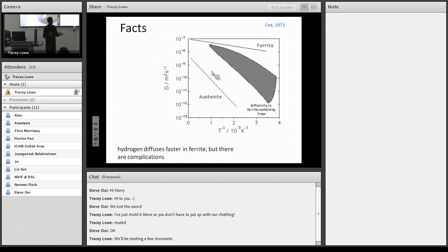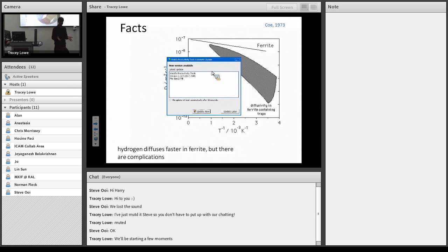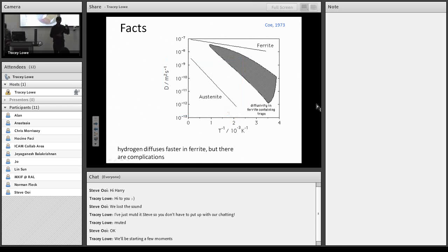So you might ask yourself the question, how can we hold hydrogen in a steel cylinder which is ferritic? I mean, you do it, right? Any ideas? How can you hold hydrogen in a steel cylinder? The diffusivity of hydrogen in ferrite is huge. Well, this is atomic hydrogen. Molecular hydrogen hardly enters the steel. So the cylinders contain molecular hydrogen, and similarly, if the hydrogen in the steel changes into a molecular form, for example, by entering a hole, that will not be able to escape out of the steel.